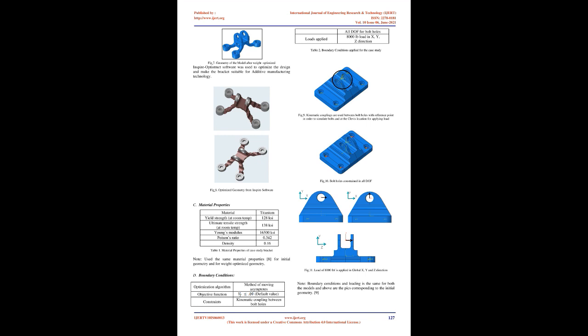Inspire Optistruct software was used to optimize the design and make the bracket suitable for additive manufacturing technology. Fig. 9. Kinematic couplings are used between bolt holes with reference point in order to simulate bolts and at the clevis location for applying load. Fig. 8. Optimized geometry from Inspire software.